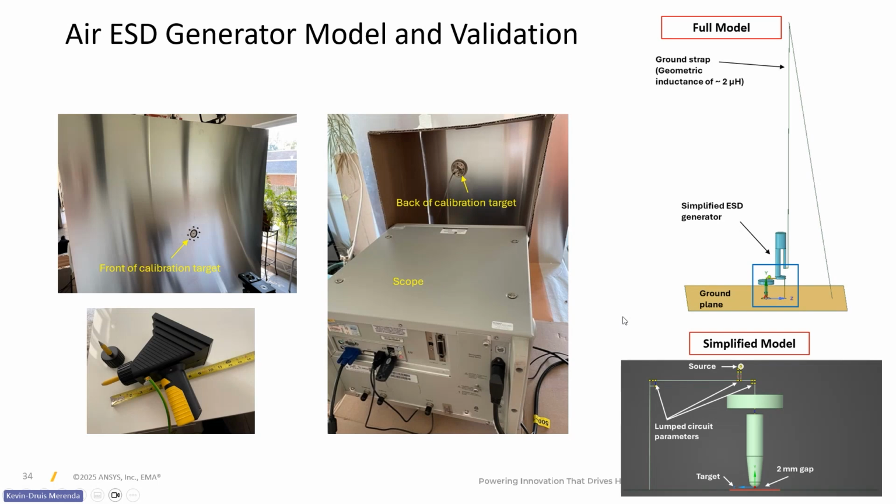The FDTD has thin wire models that allow us to set RLC terminations on them. And so that allows us to create relatively simple circuits. We also have switches for these that you can put in conjunction with thin wires. And that allows us to, again, create simple circuits in the system. If we want to go beyond that, then we can use something like Nexxim or a SPICE circuit solver that's integrated to M-harness. But within the FDTD itself and Charge Plus, you have access to the thin wire tools to be able to set these components.